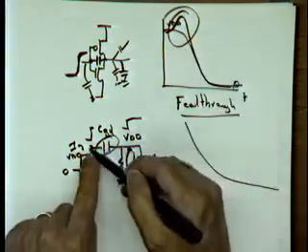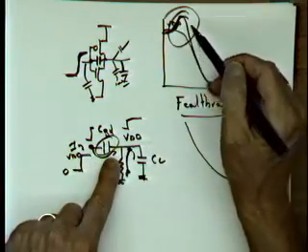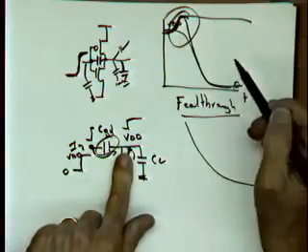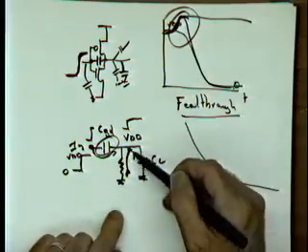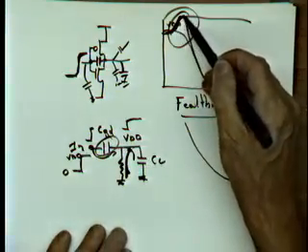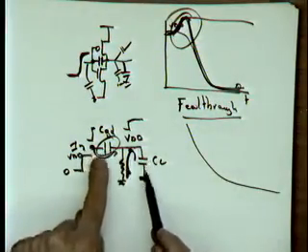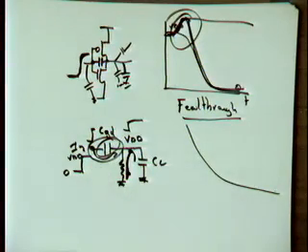So what we're going to see is that the input is going to couple temporarily to the output. It's going to go up. If you wouldn't have this resistor here, it would stay there actually. However, then the resistance comes in action and says, okay, I'm going to start taking the charge away. So that's why we first shoot up and then we go down. It's because of this capacitive coupling between the input and the output. And that's why the step you apply propagates directly to the output in an attenuated fashion, obviously. Not at the same level, attenuated, but you see it happening.